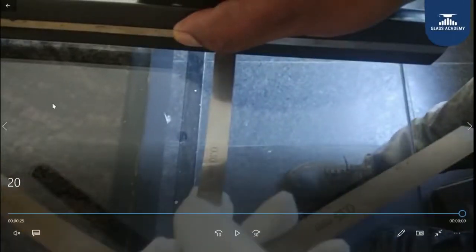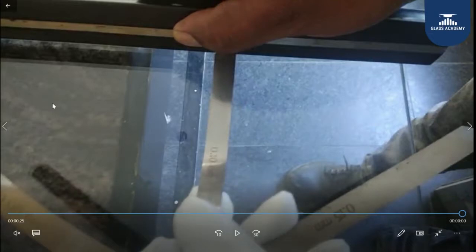The procedure for this one is, I need to take a glass on a flatness table. Generally, edge lift you get on the top surface, so I need to make sure that the glass is facing the top side as in the furnace, meaning the measurement of the edge lift should be on the top surface. It should be placed on a flatness table by leaving 100 mm hanging off the table, and with the help of a knife edge and a feeler gauge I can measure the edge lift. The measurement should be perpendicular to the direction of the glass.